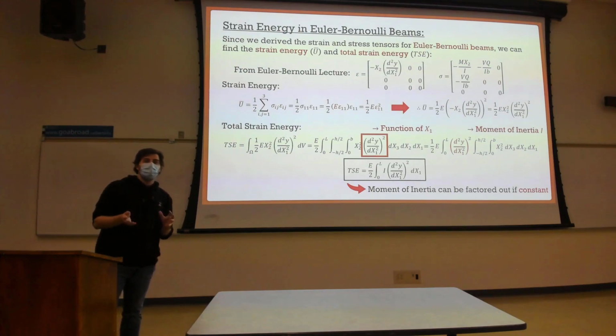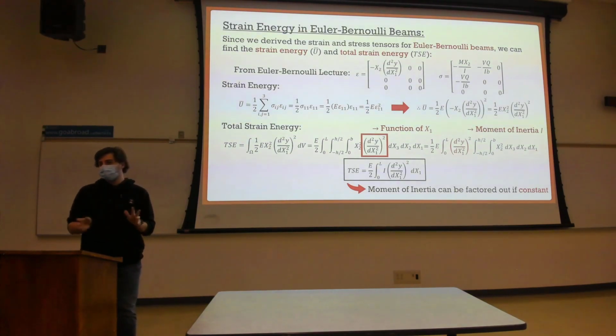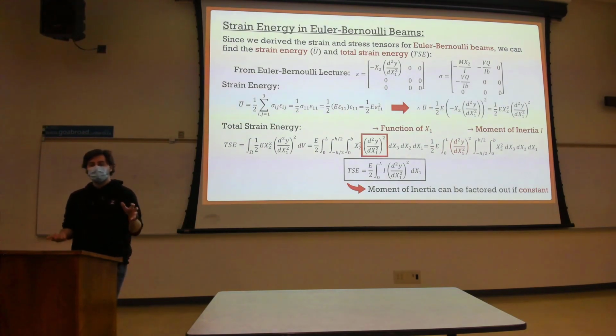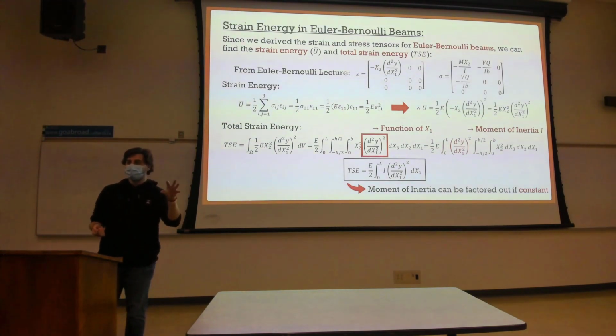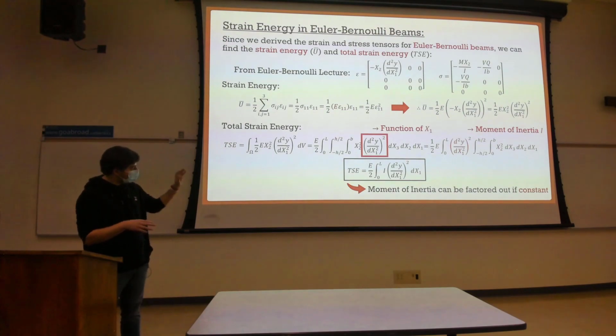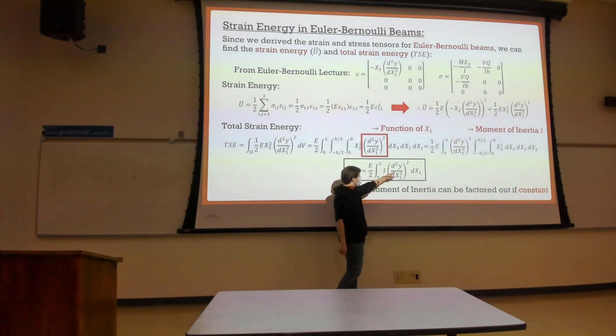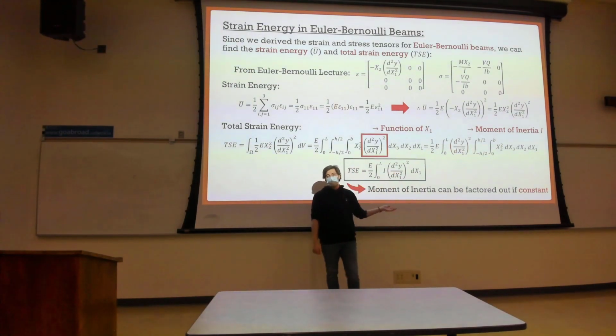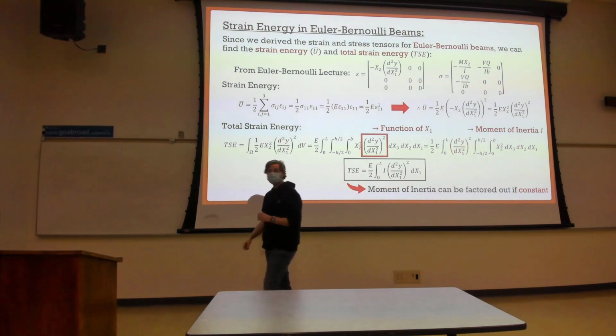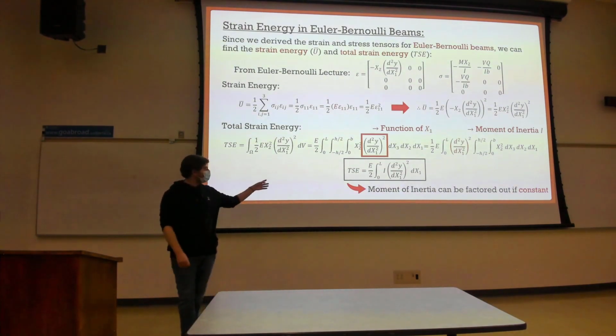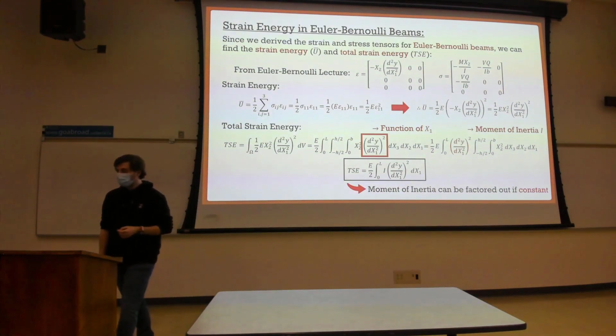Well, the Rayleigh-Ritz method is almost identical to virtual work. It has some differences. But basically, in virtual work, we take internal virtual work and we make it equal to external virtual work. The internal virtual work is basically this. The only difference is instead of y, which is our deflection function, we would have y star, which is our virtual deflection function.